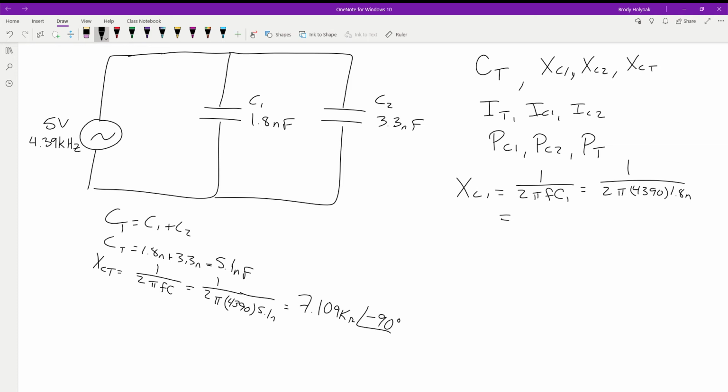Reactance. The reciprocals, yes, because at that point it's just a resistance. At what angle? Negative 90. And that is a good catch right there. Because you're like, wait a minute, my total is 7,000, but one of these values is 20,000. But then, as you were saying, you caught it. The configuration you have, now that we're in parallel, we're dealing with a resistance value. We just treat it like regular resistance. We'll put it in the reciprocal formula. Okay. So we've got that one.